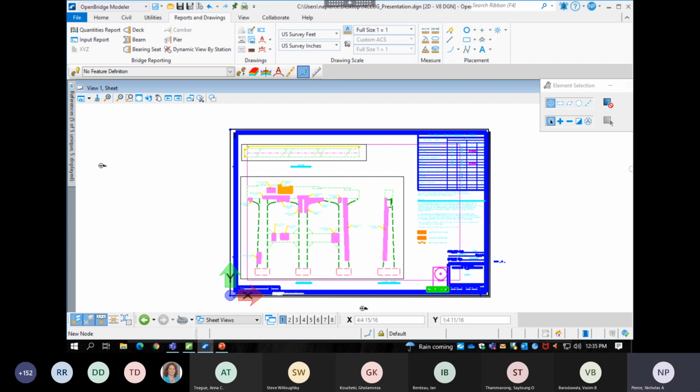All right, thanks, Steve. We did try the line style. The problem we ran into is, again, when you cut it, you don't see it, or the post spacing ended up being uniform where in real life it's variable. So yeah, and I don't know if line styles are going to give you an easy way to vary your spacing and things like that either. The line style is really going to be more just for visualization purposes only.